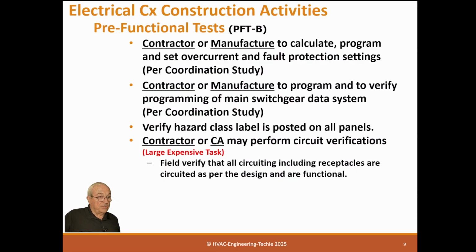The only way to do it is put a tracer signal on the circuit breaker and take a tracer instrument and put it in each receptacle to tell which receptacles are on that breaker. And the reason that's important, if a guy put 15 or 20 receptacles on it, it is now not rated for a 20-amp breaker. So those are kind of important to do. There's no really easy way to tell after the fact.